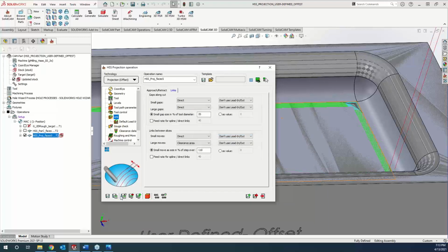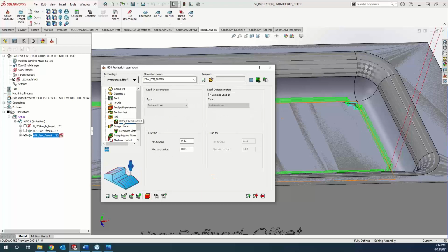Now, Kevin, after we do the direct, I say we go back to the safety distance and maybe show the lead in, lead out, because especially on stuff like this, it's nice to have a nice horizontal tangent arc that kind of has a little bit of a helix to it. That way you're coming in off the floor, kind of ramping into that cut and then back out.